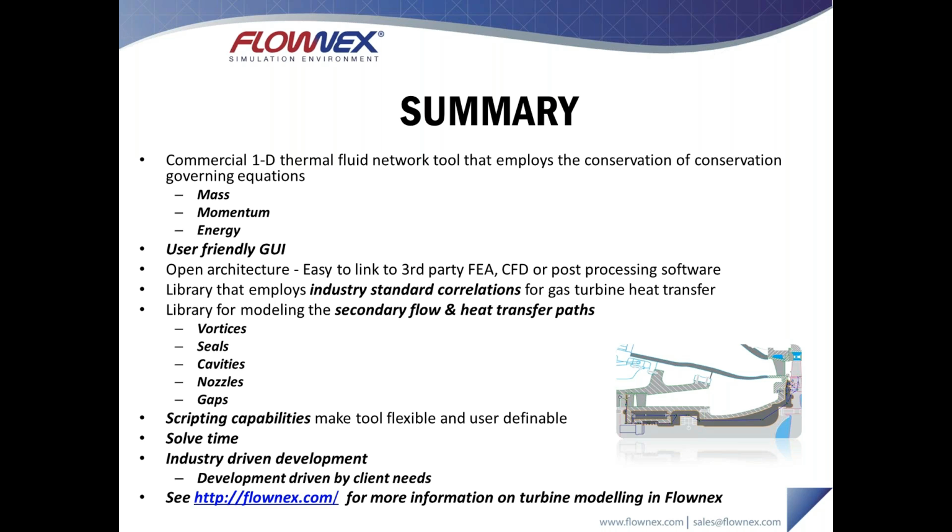The library employs standard correlations that are particular to specific industries, in this case, particular to the gas turbine industry, for both pressure drop and for heat transfer. We have many components for modeling components beyond just the turbine blade itself. So we have components for vortices, for seals, cavities, nozzles, rotating gaps. I would strongly recommend that you take a look at the webinar on secondary flow or cooling flow. These explain all of these other components in a large amount of detail, and it's definitely worth taking a look.